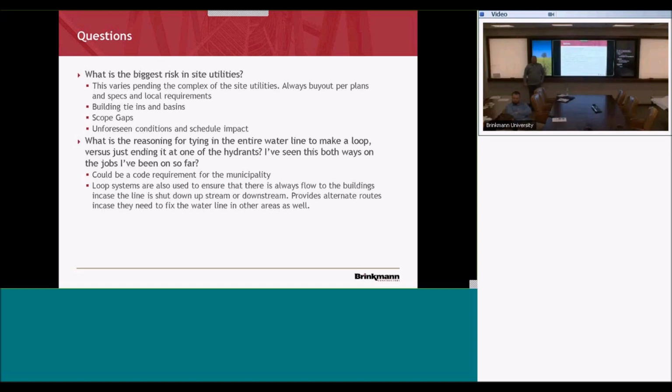Right. But, to add to what Jared said, you should be at rough grade before you have a utility come out and bury their stuff. So if you're not, you can kind of work around it, but you've got to tell them, hey, if we have to cut 2 feet out of here, you need to dig a little deeper. There's a little coordination, you can't just let them run. And in that scenario, if you aren't at grade, then you need to make sure either you're on site or your superintendent's on site while that work's going on, so you can say, hey, you're not deep enough. Because otherwise, they're going to go 30 inches below, and that's where it's going to lay.